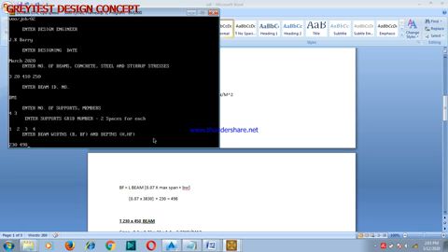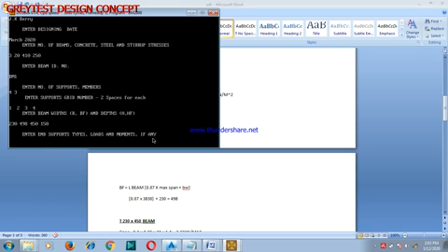Now what is the depth of that beam? Remember we said it's a 230 by 450 beam 1 to design. What is the HF? That's the height of flange. Height of flange is the part of that beam that enters into the slab. That's the thickness of your slab, which is 150. HF. Now enter end support type, loads, moments, if any.